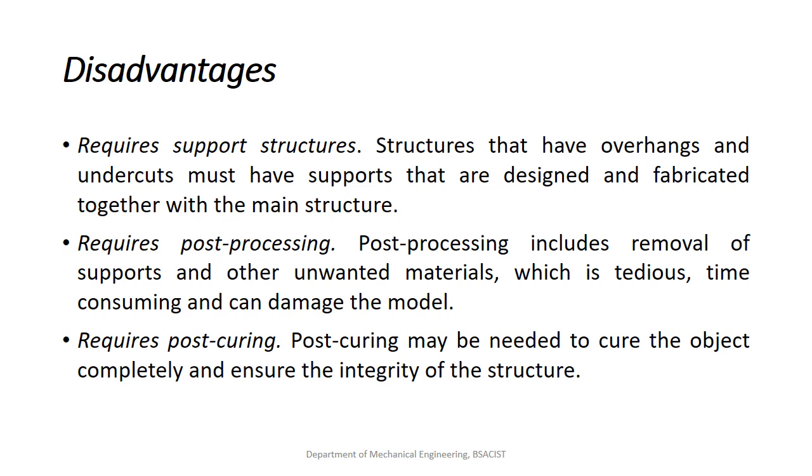One of the main disadvantages is that it requires support structures. Overhanging parts cannot be made as such; we need support structures to support them. So it requires post processing, which involves the removal of the support structures and unwanted materials, which can be tedious and time consuming. If not done properly, it may also damage the model. Post curing may also be needed to cure the object completely to ensure the integrity of the structure. Post curing improves the strength of the part produced.